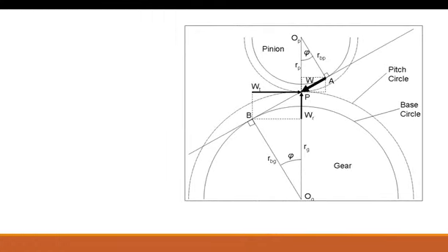Now, we do more than just try and change speeds with gears. Gears also are used to do a lot of mechanical work. You know, if you have a vehicle and you have a lot of heavy load, you might need to shift it to a lower gear. If you're on a surface and you need to get better traction, you might need to shift the gears in order to get more force. So it's not always about getting more speed out of the system. Sometimes you need to be able to transmit more torque throughout your system, or less torque, which allows you to get a little more velocity out of the system.